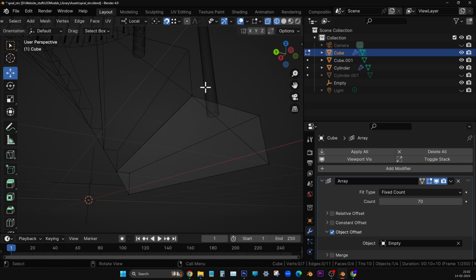Previously, what we did, we drew a rectangle and selected, right? Because there were two vertices, so we had to do the rectangular selection. Now, because I am confident that it has merged, I am taking my cursor and just doing a quick selection because there is only one selection. It is a single object, or single vertex, or single face, or single edge.